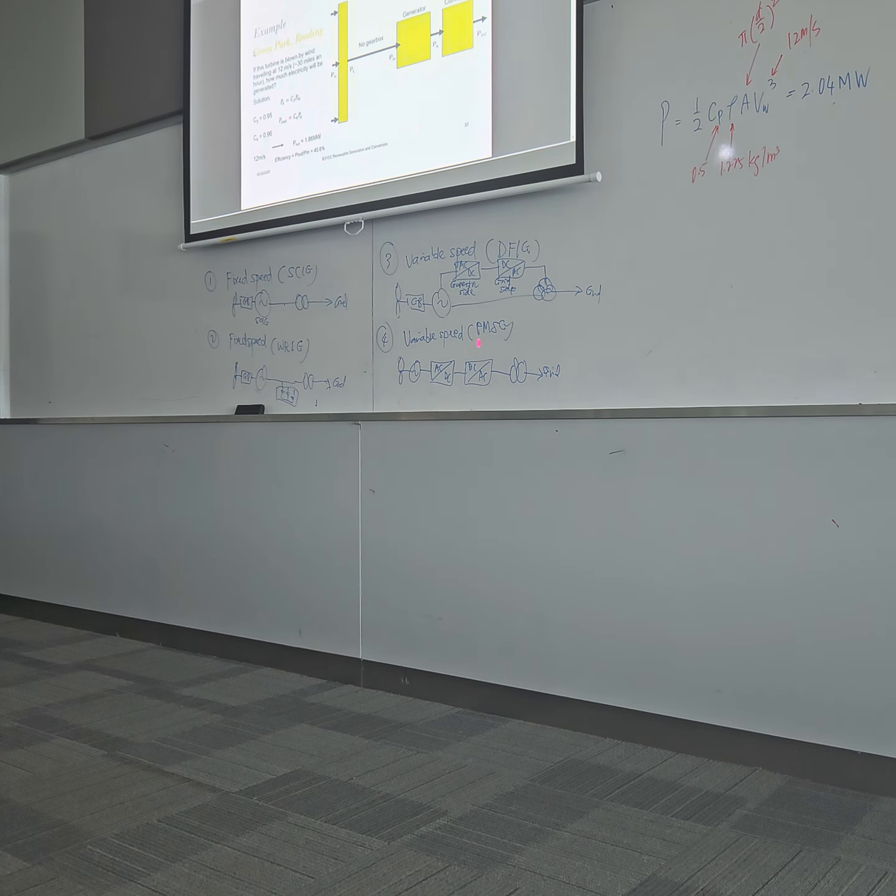So after that will be the generator, which will have an efficiency loss, let's assume 0.95, and then the converter loss, which is 0.96. So in total, your output power will be 1.86 megawatts. Okay, if we consider the input power just now, 4.07. So 1.86 divided by 4.07, you will get an efficiency of 45.6%.